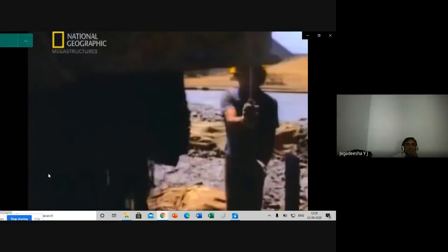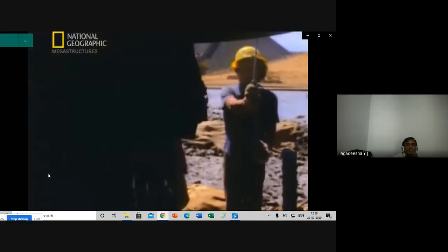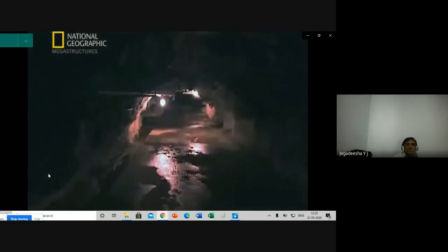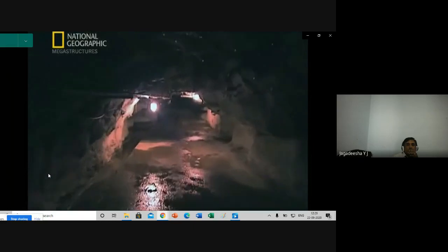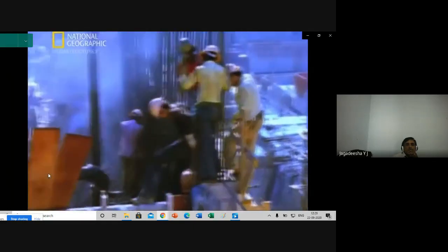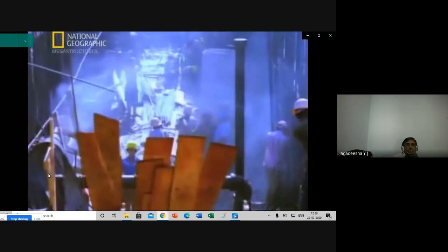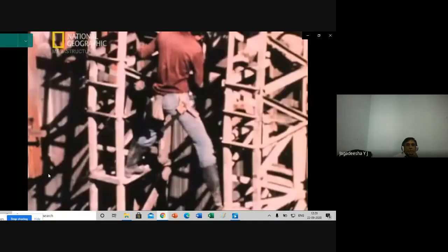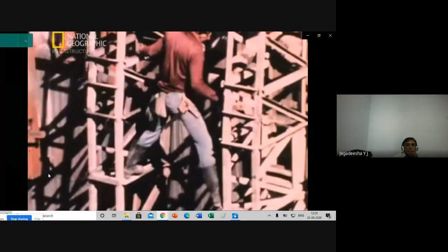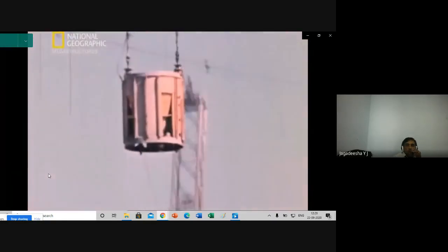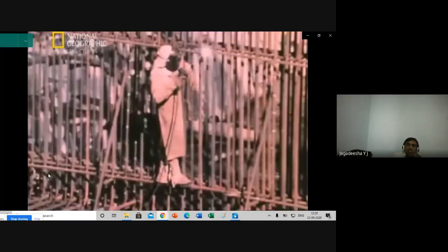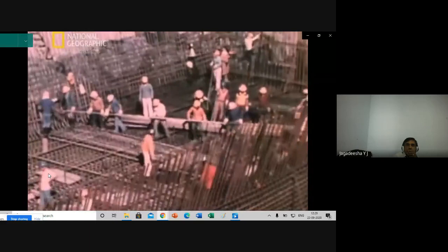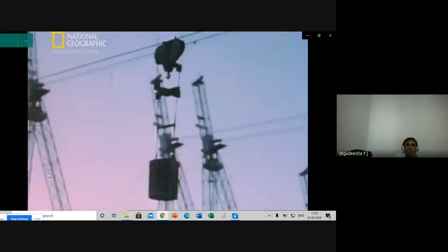Like a bad tooth, the rotten rock layer beneath the Itaipu Dam site was drilled and filled with extra strong concrete, so that it could take the weight of the dam. At the same time, work on the dam's giant central walls continued. The construction team set about casting 18 massive concrete blocks. Each block had to be made separately. Huge steel structures were erected to receive the concrete and hold it in place until set.